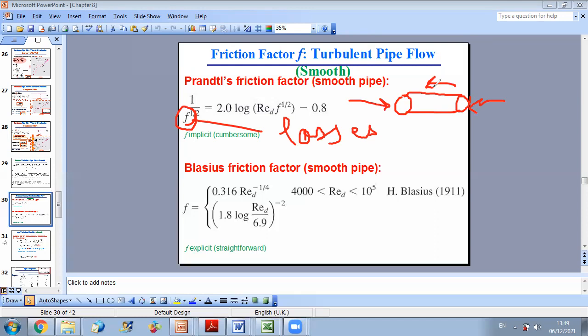Now, in analytical cases we were able to compute the friction forces analytically, while in turbulent cases it's not simple to do. This is why we defined a dimensionless number related to friction, which is F. If you remember, we defined last time what F is. We'll see it in a while again. F is related to losses HF, which is the head loss due to friction.